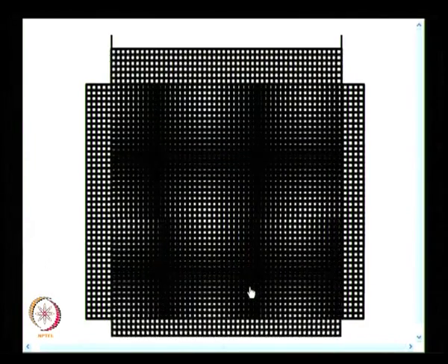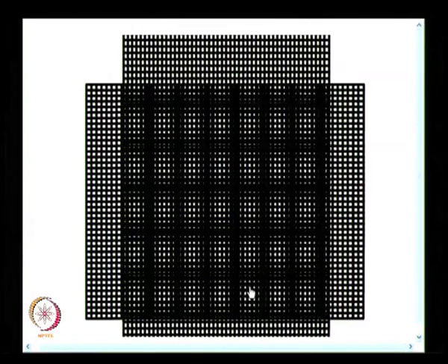So, that means you have to interpret horizontal fringes separately, because we have always seen that whatever the fringes perpendicular to the grating direction, you will find out whether the grating is aligned in the x direction and you get the v displacement, if the grating is aligned in the y direction, you get the u displacement. Here I have a cross grating, so I get u and v displacement simultaneously.